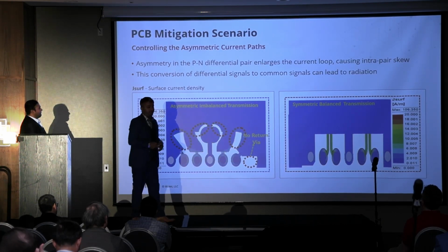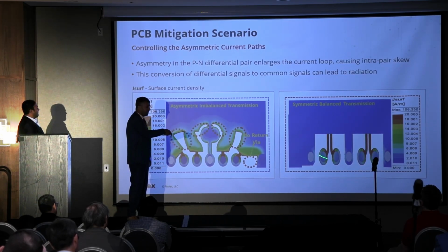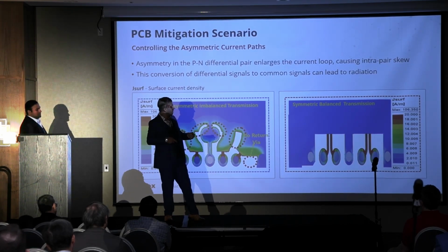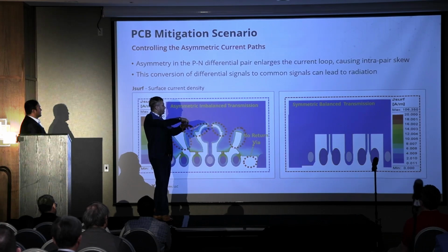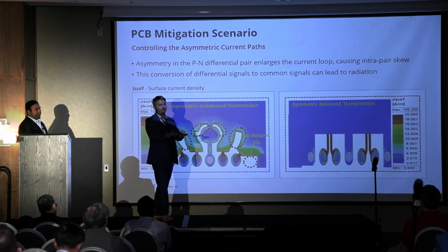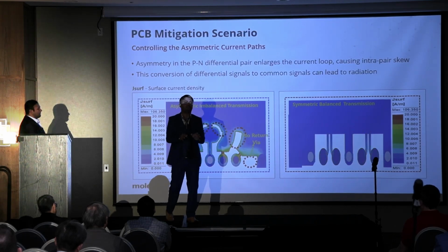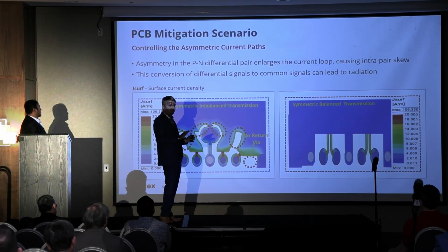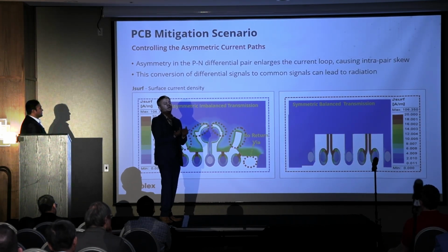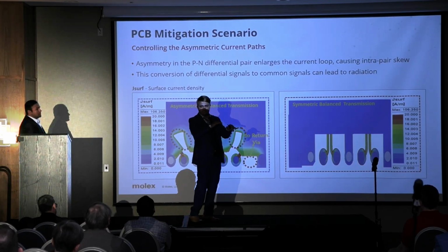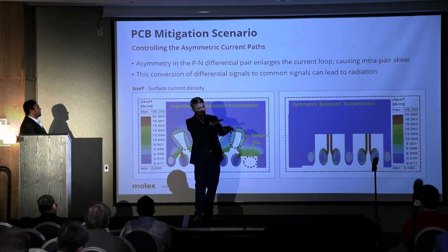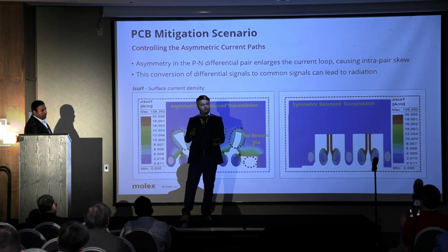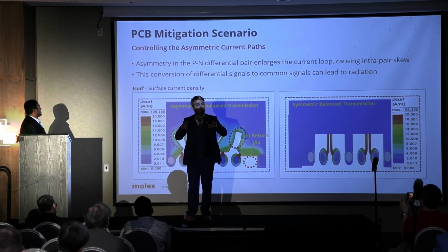In this particular scenario, the reason we have shown this area is so you understand that this is a very critical area in a PCB design, where we have a connector and a cable, because the connector would be connecting in this region, right? Signal would be propagating on a transmission line, in a TEM mode like in a stripline. Once the signal reaches this antipad region, it starts flowing into the via and coming up. When it is flowing in a transmission line, the return will be below. The P signal return on the P line comes towards the via, and likewise the return signal on the N line. One will be clockwise, one anti-clockwise, going towards the via.